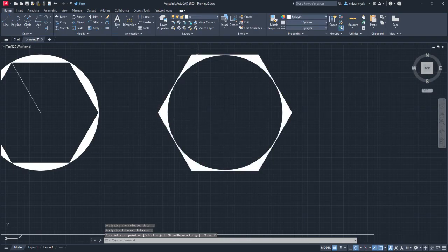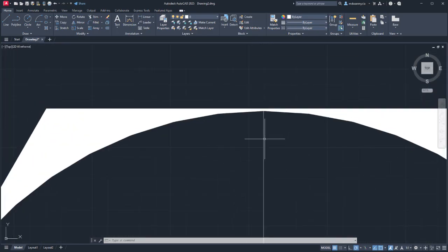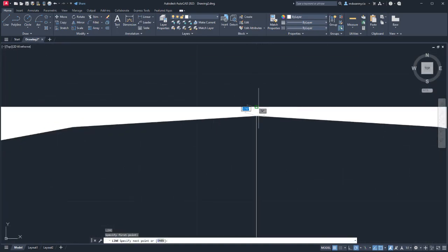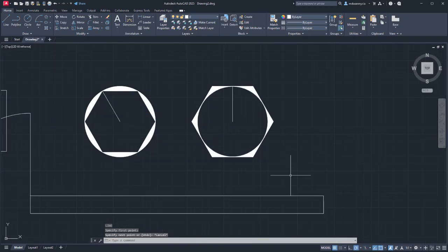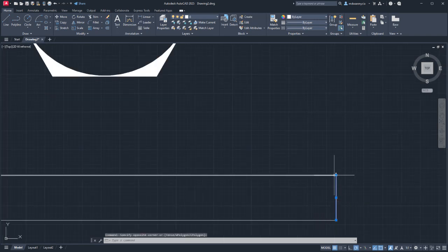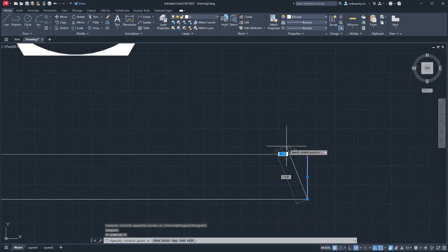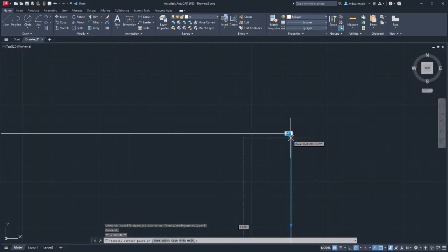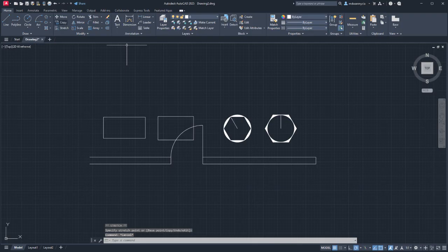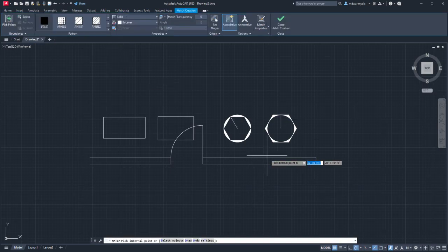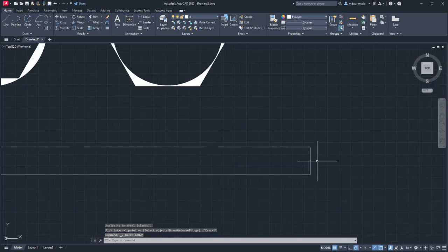So there are times where this tool will work differently, and I guarantee it's because you have just the tiniest weird gap somewhere. What is this right now? See, it's rounding it to a 16th, but that's a 1/8 right there. So yeah, it's a tiny gap, but it's going to change how this draws. So you guys will very likely have issues with it at some point. Similarly, you go to fill in, say, the walls of your project, and you run the hatch, and that was too small.